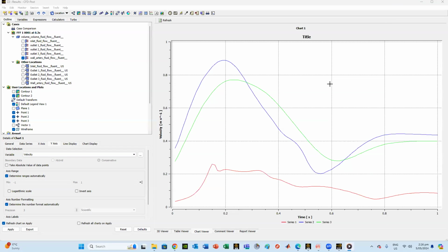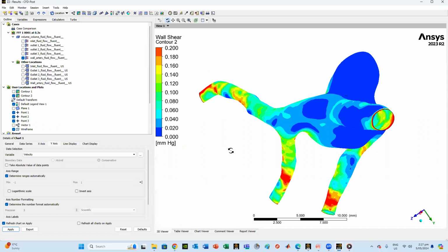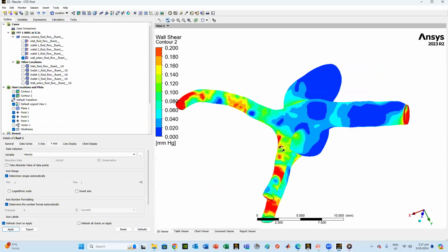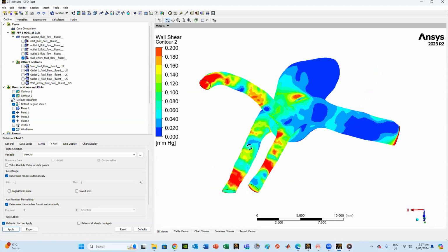So yeah, after running these, you can see clearly the velocity profiles for the 3 points which I identified earlier, 0.1, 0.2, 0.3, and you can see how the velocity responds with change of the time. You can see there is a time shift between them, which is something good to see in this type of model. So definitely the model is working, and I can see really good outcomes from it.